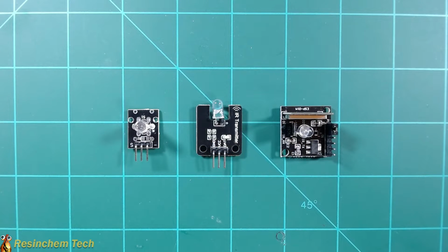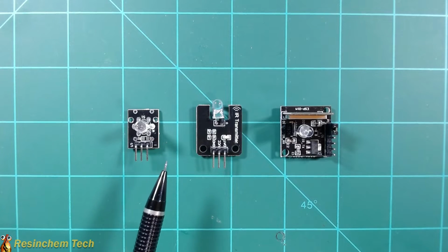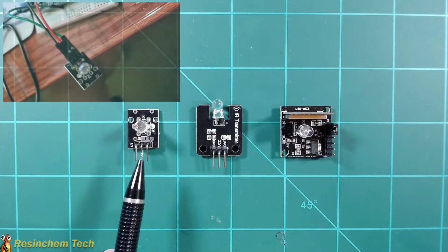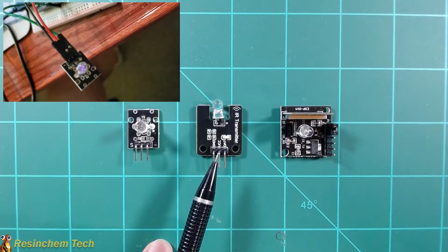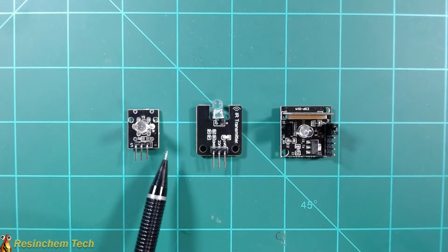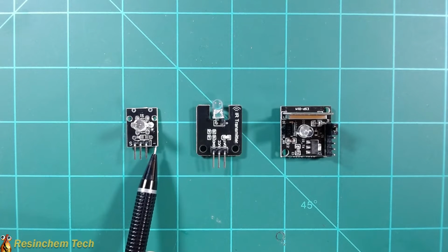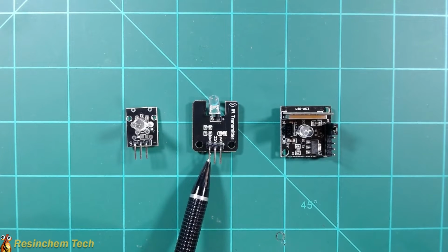And speaking of range, I did actually test a couple of different options, partially because I was having an issue without getting any IR transmission at first. And it's kind of hard to troubleshoot that because you can't see anything from the LEDs with your bare eye. But if you use a cell phone camera, you can see when these are or are not transmitting. It was resolved by using a different GPIO pin. I talk about that in the blog. But in my testing, I did find this KY005 actually had the best range, almost double the range of this particular version when used with the logic level shifter.